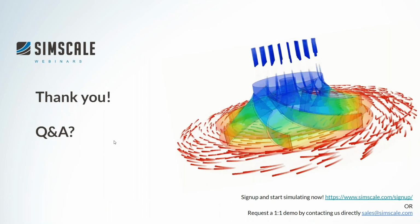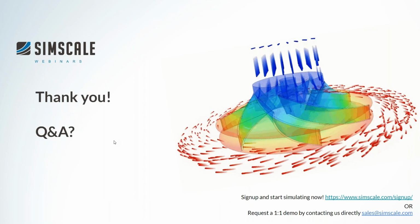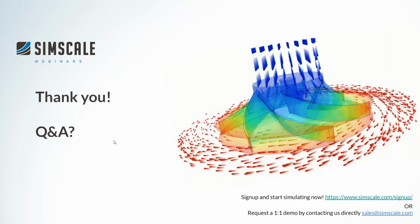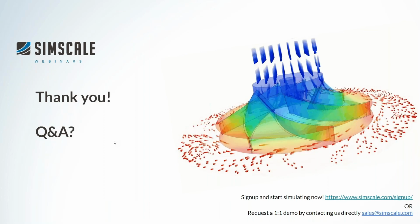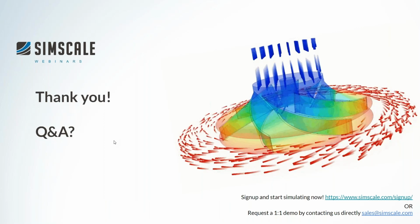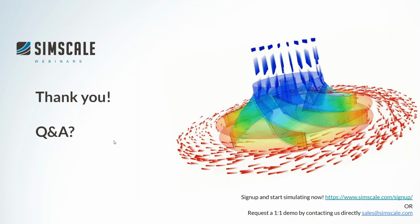Thank you, Mattia, and sure, something for us to get back to the attendee with the answer. Another question coming in is, does this simulation include cavitation effects? I can probably answer that: this simulation particularly does not include any cavitation effects. This was a straightforward steady state simulation. We're using the MRF method. But in general, in SimScale, you can include cavitation for pump or hydraulic equipment simulations.